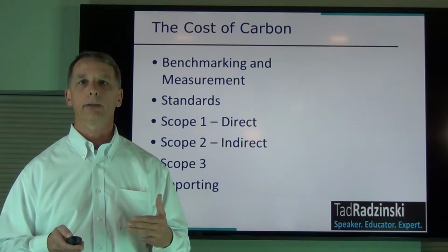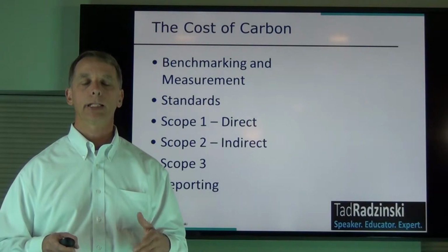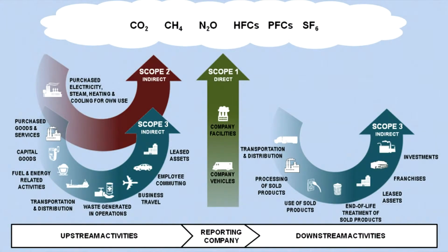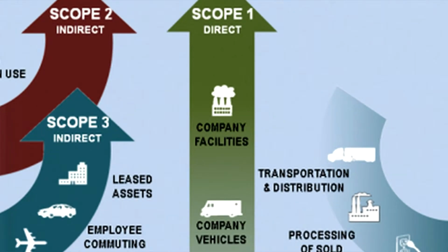The other thing you're going to be looking at, as I mentioned, is what we call direct emissions and indirect emissions. Direct emissions are going to be any fuels you burn on your site. So let's say that you're burning natural gas in your rooftop units for heating a building, or you're burning fuel oil in a boiler to make steam. Those are definitely fuels you want to capture as direct emissions because you're combusting them on site. Also, any vehicles that you use on site, whether it's forklifts or trucks, or cars that you're running around with on your site, you definitely want to capture under direct emissions.